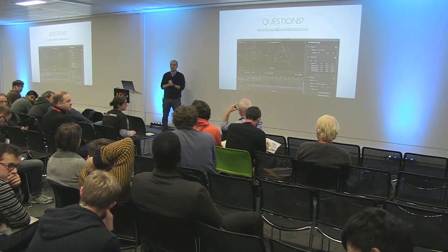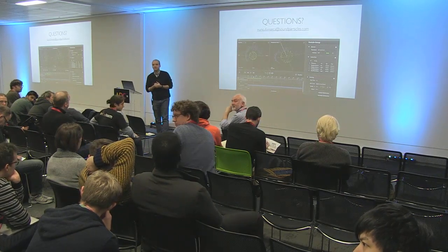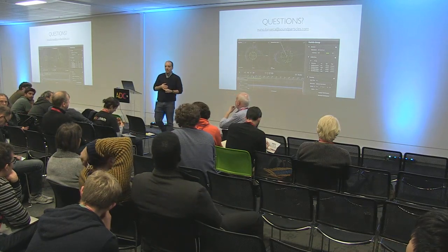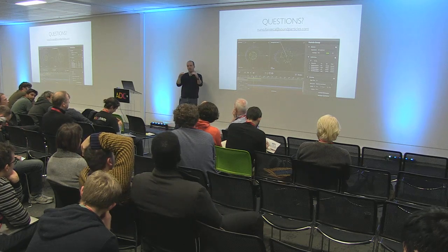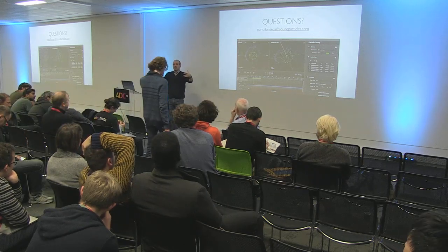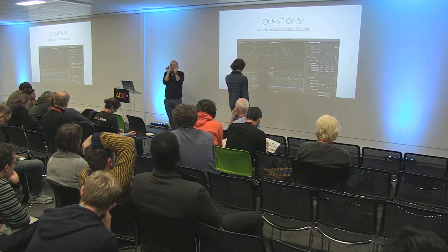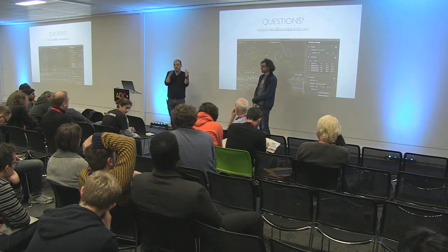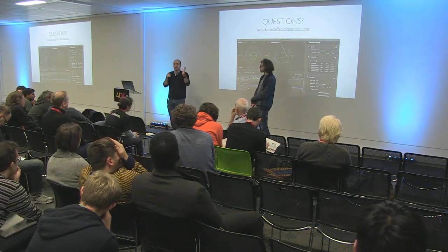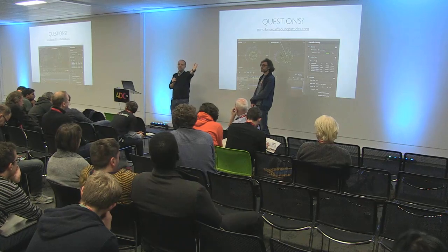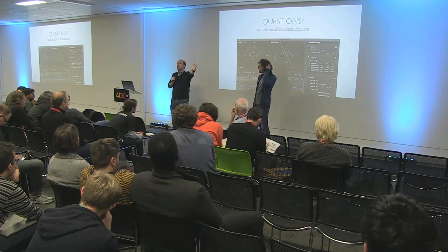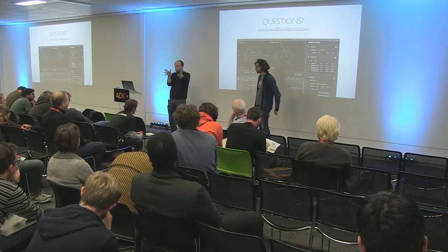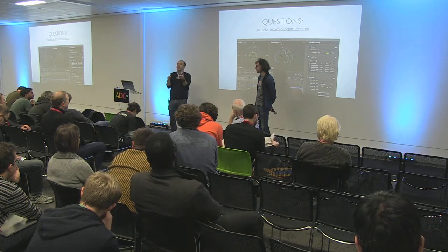Is it possible to calibrate the binaural experience individually? There are people trying to do that. For instance, imagine that you get the data set, but the person has a head that is slightly different, so eventually you make some kind of adjustment. Imagine that you place something that should come from 45 degrees to the side, and you ask the user, this sound, where do you think it is coming from? If they say it's at a slightly different position, you use that information to slightly calibrate things. So yes, it's possible.